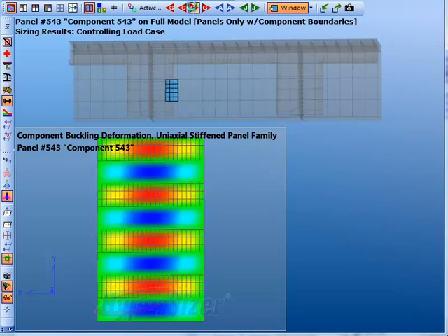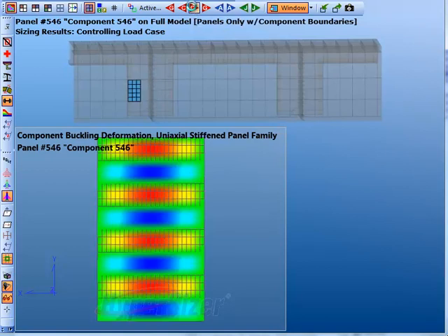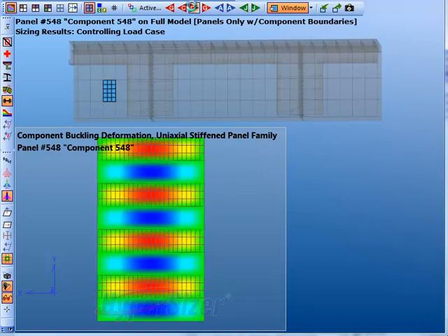These buckling solutions are not performed with FEA. They are being done independently of the FEM mesh, which is how variables, such as stiffener spacing and heights, can be evaluated dynamically. The Rayleigh-Ritz energy solution is extremely fast and allows HyperSizer to analyze panel buckling to thousands of candidates and hundreds of load cases for a quick optimization turnaround.